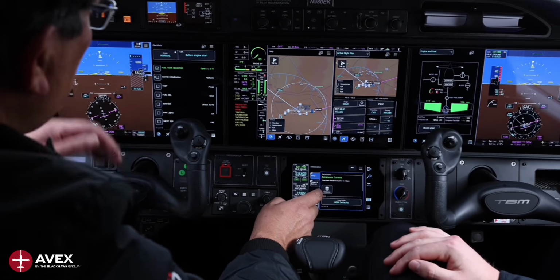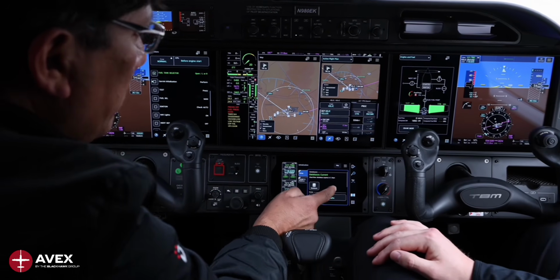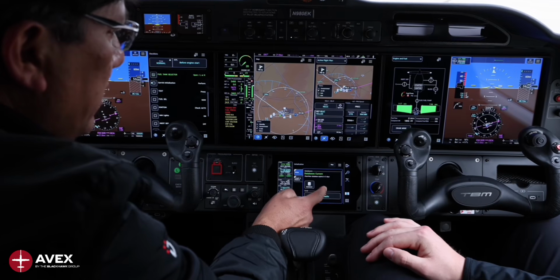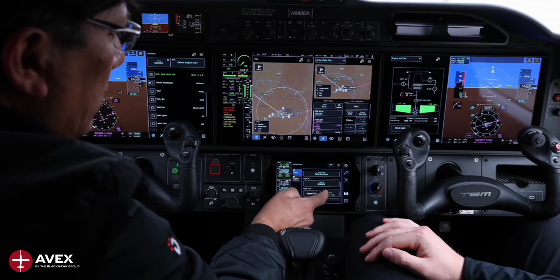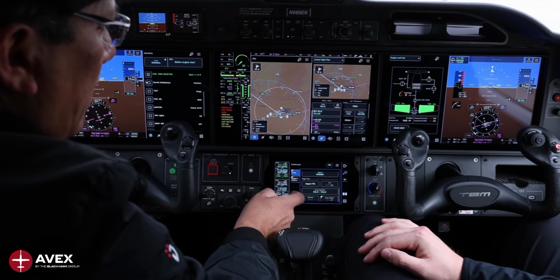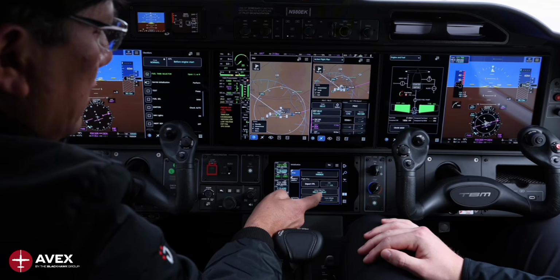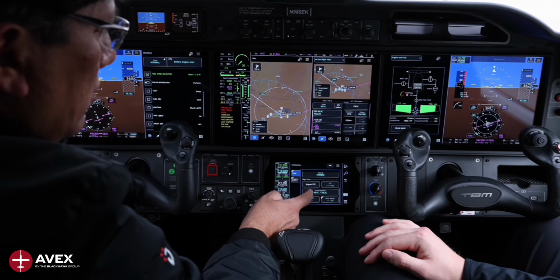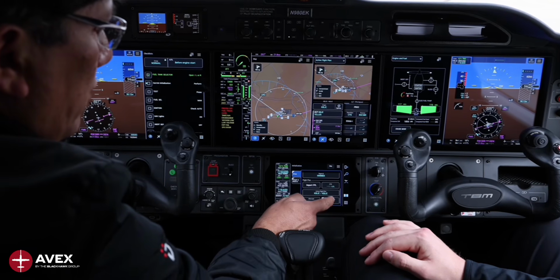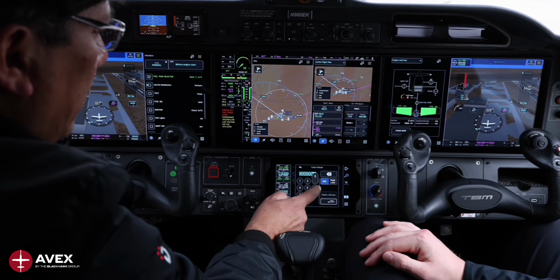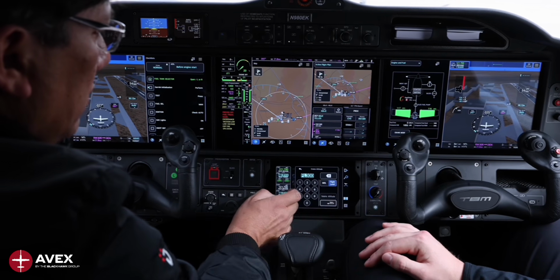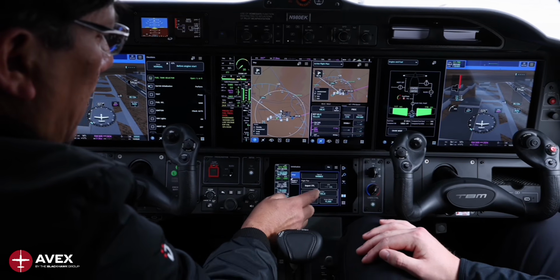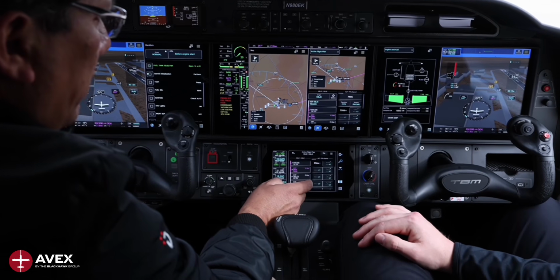Okay. We still have the initialization. It's a lot simpler on the 980 than the 960. We just scroll down and we have here, for example, Metro to Metro Airfield. We put what flight level we're going to fly. Let's say we're going to fly flight level 300, enter, and there's our flight plan.